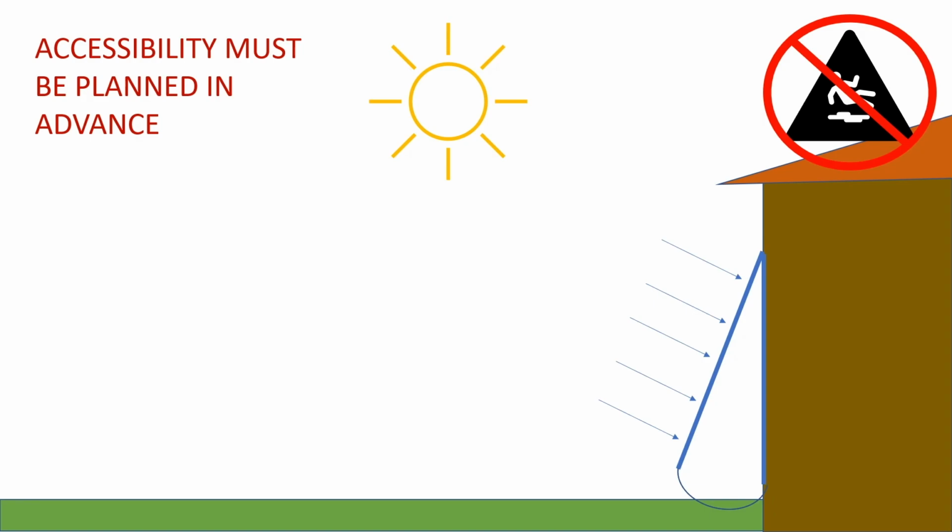For the mounting at the optimum tilt, we are facing the ice and snow clearing issue, which might be particularly challenging on a steep rooftop. Climbing on icy roofs is extremely dangerous and should not be attempted. Thus, safe access is something to consider when selecting the position for the modules. The one-off access when modules are mounted is not the same as regular maintenance access. It is the main reason why many use their garden space rather than the rooftop for solar modules. Obviously, this depends on the availability of such space and the expected frequency that maintenance is required, for example cleaning in very dusty areas or, like in our case, removal of ice and snow.